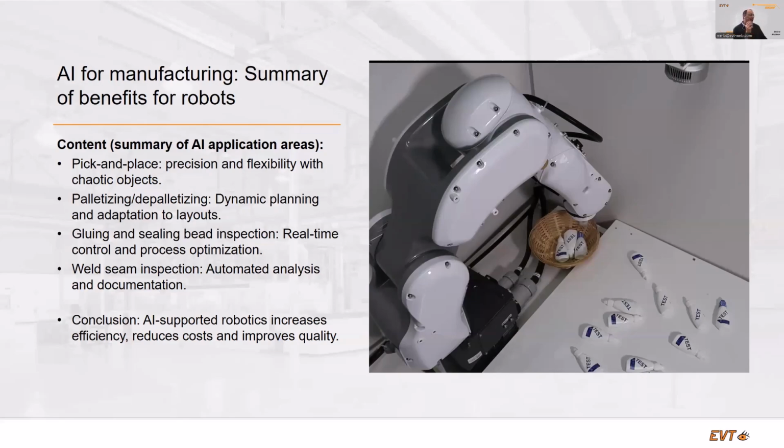So that's why we say AI is a real advantage in many applications, such as palletizing and depalletizing, especially if you have a pallet with different parts on it, which are difficult to recognize, maybe because all are cardboard boxes, but with different sizes, and they are very close together. It's difficult to recognize the position, the orientation, or where the boxes are. The AI will tell you, look, I see the boxes, and then with the information where the box is, you can simply use the 3D information to grab it at the right position with the right gripper. So it's a real advantage for machine vision solutions.